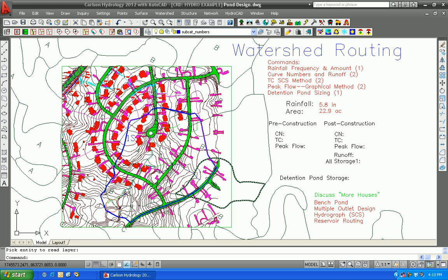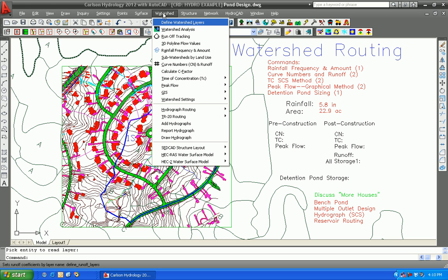That led to the completely automated calculation of your composite curve number of 62 inside this blue perimeter. Completely automatic. There's a lot of cutting of one perimeter against another going on in this process. It's almost a GIS style process to get the composite curve number by SCS method.